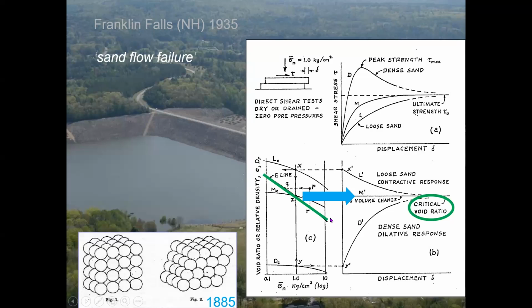So we say, okay, we're going to take that as an axiom. And the nice thing about a unique endpoint is it means the mathematics, or our applied mechanics, is well conditioned because we know where we're going. It's very easy. If we define a deviation measure, that is our current void ratio, and we subtract from that the void ratio in the critical state for the current confining stress, we call that the state parameter. This whole framework can be represented by the statement that the state parameter goes to 0 as the distortion goes to infinity. And that captures the essence of Casagrande's idea.